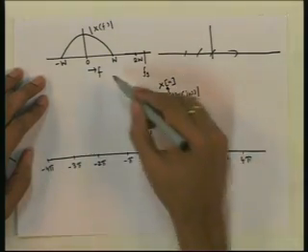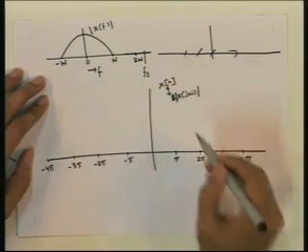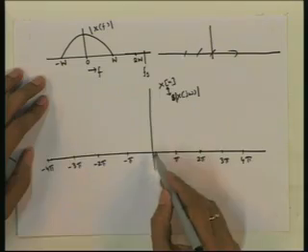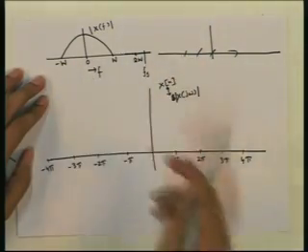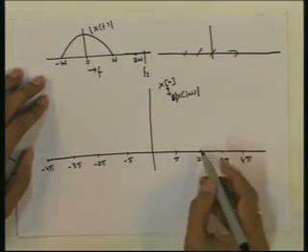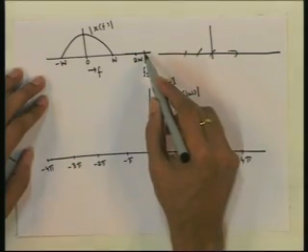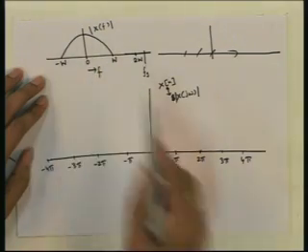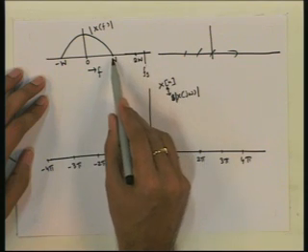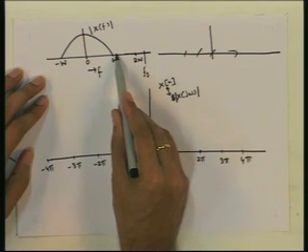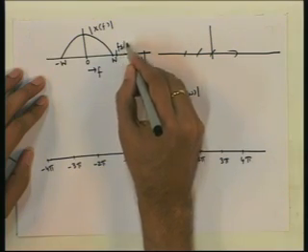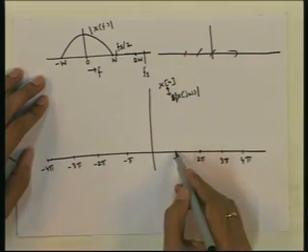So, how will we get that? This Fs will be mapped to 2 pi frequency and 0 will be mapped to here, and then the rest of the frequencies will be placed linearly accordingly. So, 2 pi is Fs, and so this will come here. Since Fs is greater than 2W, this W will be less than Fs by 2, which is somewhere here. Fs by 2 is somewhere here, and Fs by 2 will be mapped to pi.